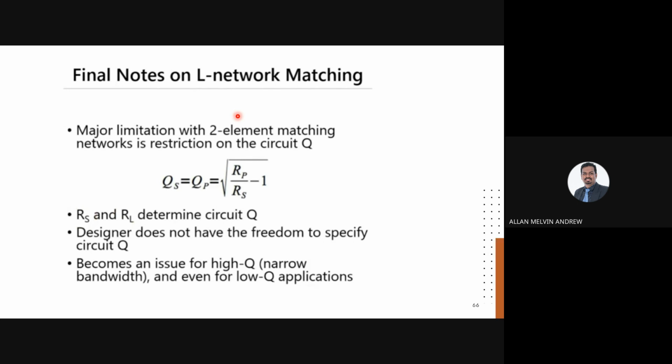Impedance matching is actually you are calibrating the frequency that is modulated before you pass it to the antenna for the transmission. You need to have certain parameters or matching in order to achieve proper transmission between the antenna and the circuit. So impedance matching happens in between the modulated signal circuits and the antenna.